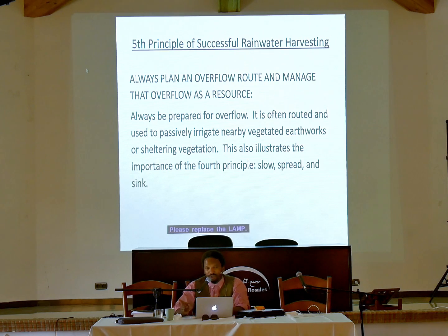The fact that we saw the type of erosion on some of the swale features is an indication that the way the overflow is being managed needs to be improved, because right now the overflow is causing more erosion in some of the areas on site.